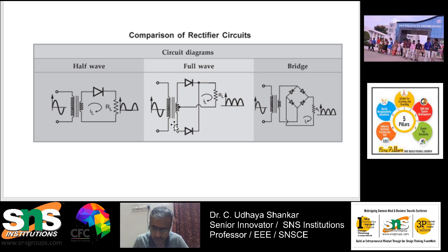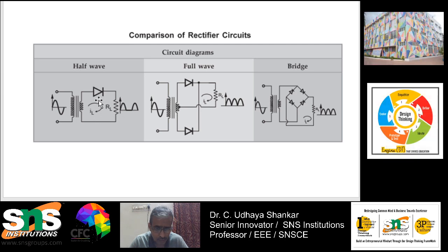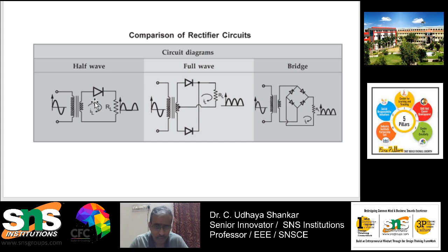Okay. So, here you will be having only one diode, and you can see that whenever this diode is forward biased, the phase and neutral will be changing in an alternating fashion. Whenever the positive cycle is there, this diode will be forward biased, whereas during the negative cycle the diode will be reverse biased. As we have already discussed, whenever it is in forward bias condition, the diode will start conduction mode, whereas in reverse bias condition the diode will not conduct.